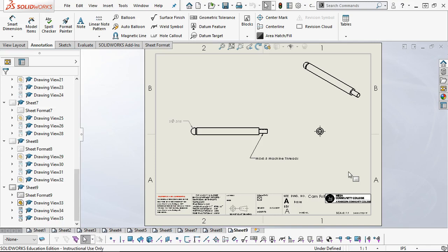The multi-body parts have the advantage of relating everything into one part with multiple bodies, which in the case of an assembly, a purchased part is what I typically will tie it into. Or in the case of the base, where it was a casting and we're trying to break it up into its components to make separate pieces and make it manufacturable, then the multi-body applies.